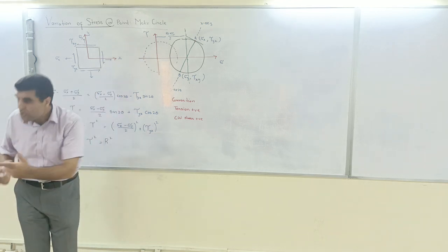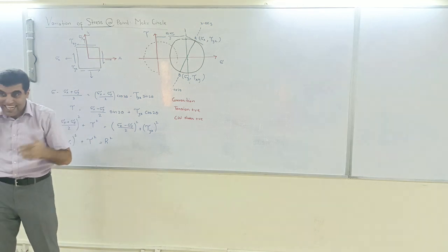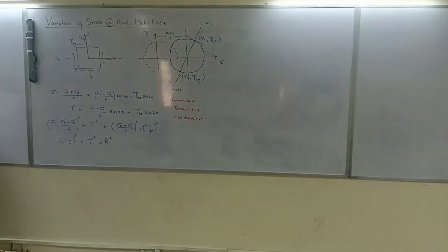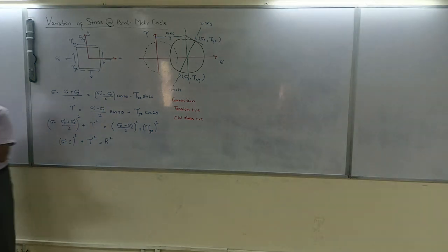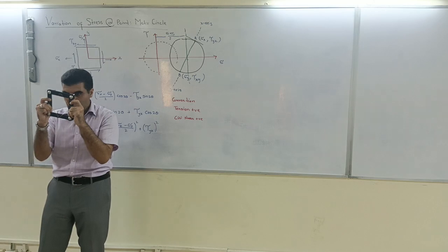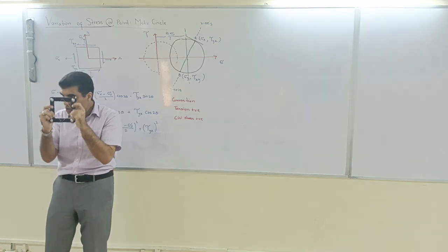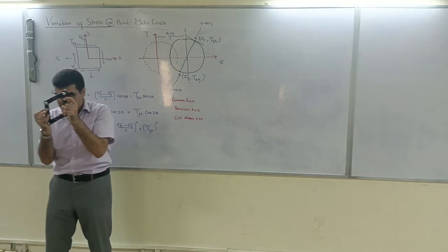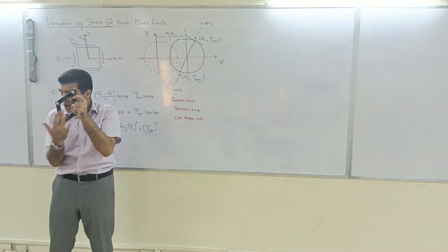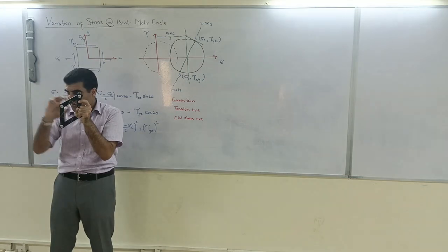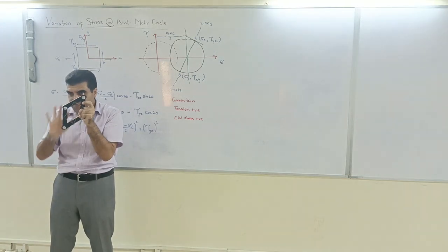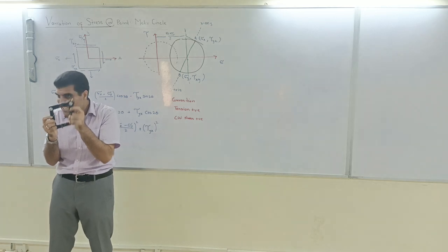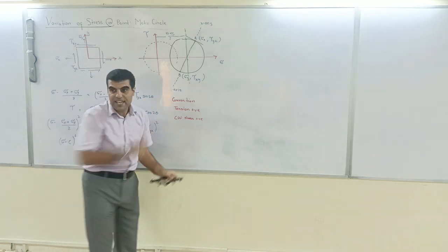And I told you that in reality that is at 45 degrees. So you see, that is backed up by this model. Look at this now, I'm moving it. This is the shear, and this box is at 45 degrees to this face. This is at 45 degrees, not 90 degrees. So in reality, this is at 45 degrees, but on the Mohr circle, it is at 90 degrees.